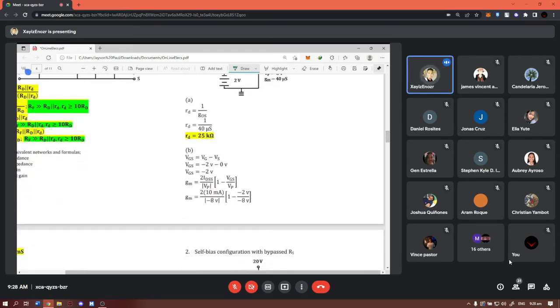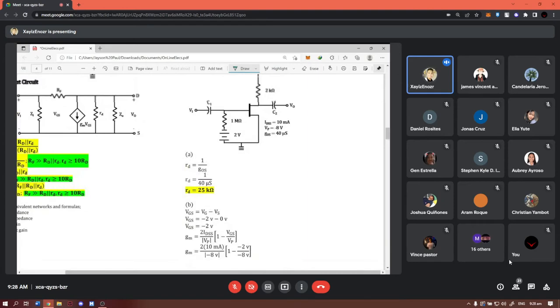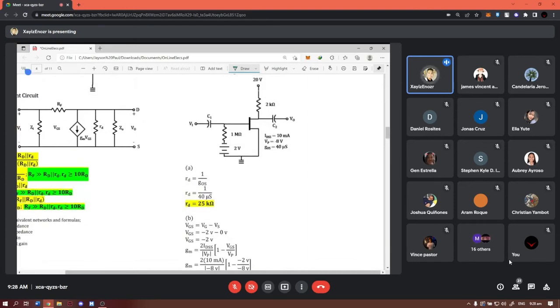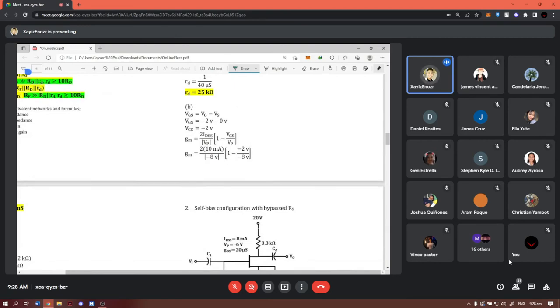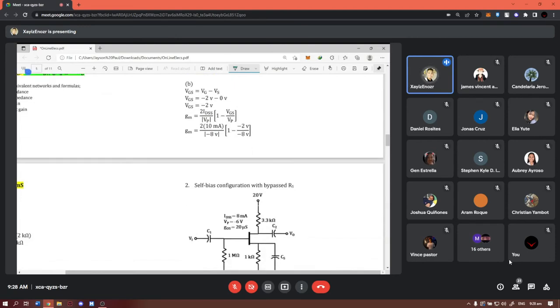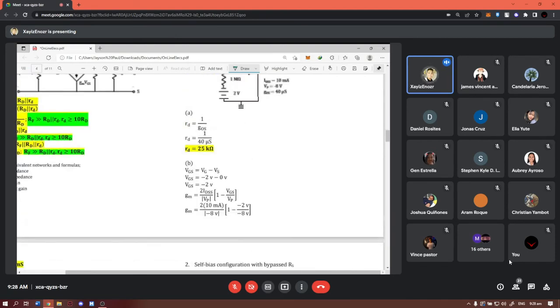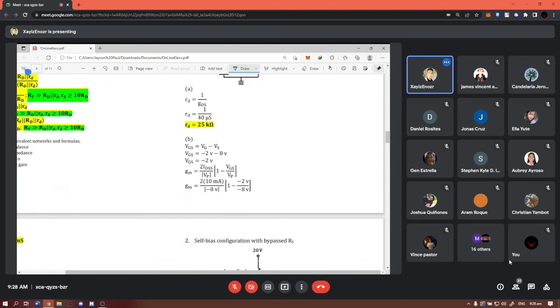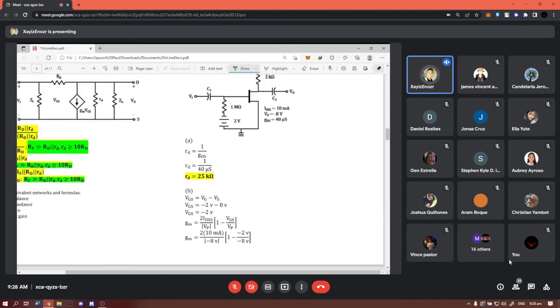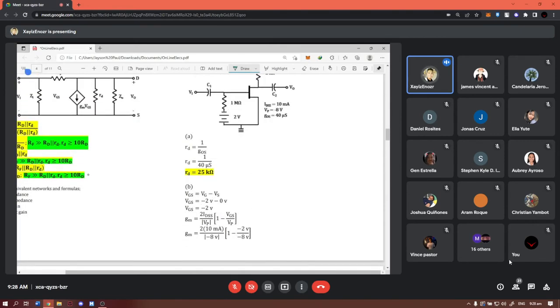Then we have here, let's now analyze yung circuit. DC analysis muna, okay? Kasi kailangan nating mahanap si VGS. So VGS, ano VGS natin? So double subscript voltage, that is VG minus VS. Makita naman natin, ang VG natin is negative 2 volts. Ang VS is 0 kasi shorted siya sa ground, so 0 volts siya. So therefore, VGS natin is negative 2 volts.